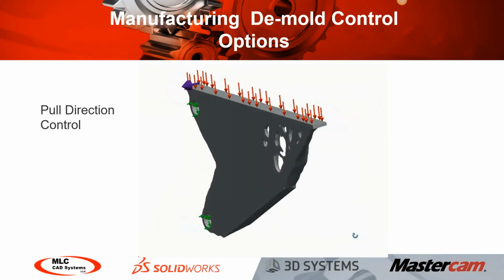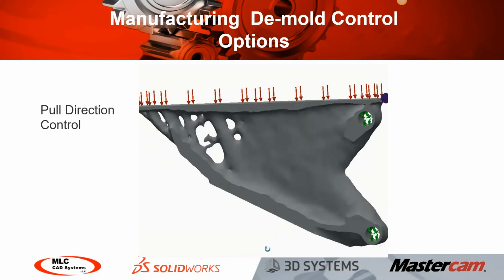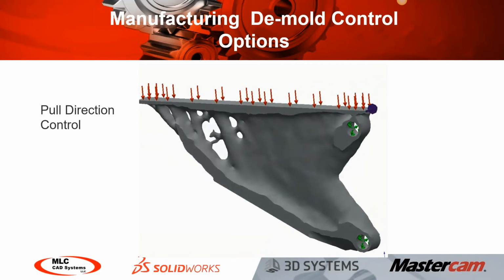And then finally, we have a pole direction control. In this case, we pick a plane and the material is removed in one direction from the plane. So this would maybe give us a part that is easily injection moldable. It would be easy to remove this part from the mold.